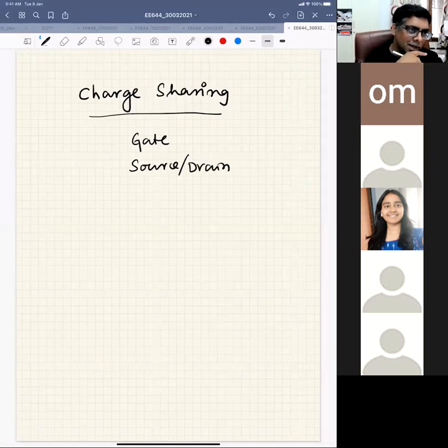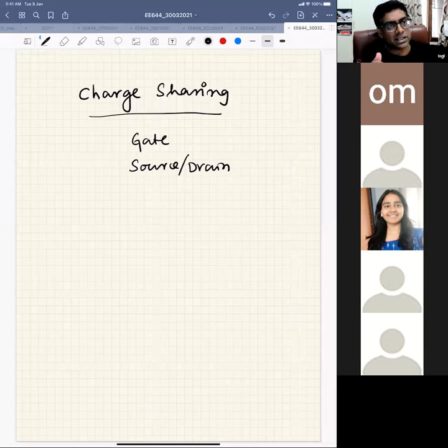What we have studied, if you look at the MOS transistor operation, is that we always assume that gate is controlling your body, right? Basically, when you apply gate voltage, you have some charges in the silicon, and based on those charges, your threshold voltage is defined, your current is defined, your capacitance is defined, everything is defined, right?